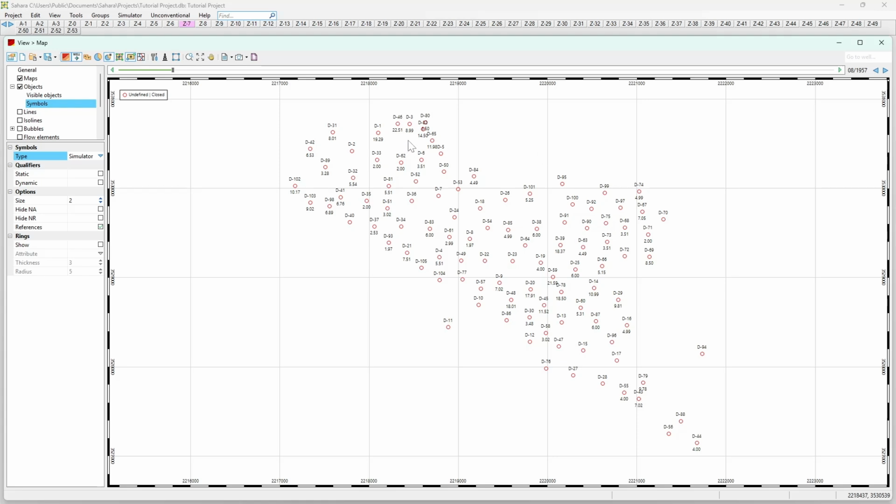But it should also show us when that well is open in that layer, but we haven't yet loaded that information. So in this case, what we are going to see is that the status of open or close is going to be undefined because that information hasn't been calculated yet, or hasn't been generated or imported yet. That information is going to be on a per layer basis. The only thing that we have now is the object status that is defined on the well level, which means that we don't know exactly where we are injecting or where we are producing, but we know that the well is either an injector or a producer. We don't know in which layer we are producing or in which layer we're injecting yet in the status sense.